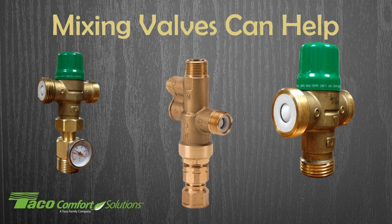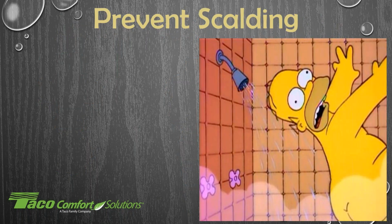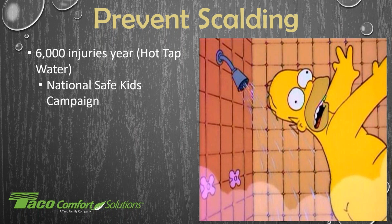Now, when people start thinking about mixing valves installed in a residential domestic hot water system, we think of mixing valves for a couple of reasons other than getting more hot water. The biggest reason is to prevent scalding, to really control your water temperature in the house itself. So that's one of the biggest things. And we see this a lot of times code-wise, that we need to install mixing valves in our house because of code and making sure we're controlling the right amount of temperature going out.